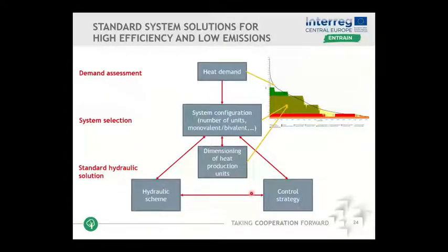We often see the mistake within the QM process that they choose a hydraulic scheme. They say serial, parallel, two boilers with storage, without storage. And then they think, oh, it's the piping, maybe some measurement points, and that's it. This will not work without a tailor-made control strategy fitting to your plant setup and your hydraulic scheme. So it's an overall concept, including all these aspects.